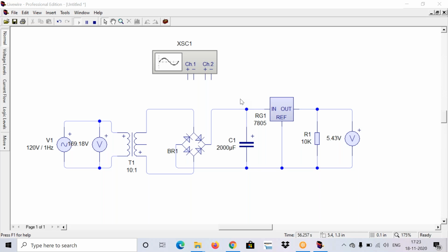Okay, I did not get you. Come again. No, sir. Our output is, we are preparing the 5-volt charger, then only you can go with the bridge rectifier. Whatever the circuit may be, whether it is a 5-volt charger or 12-volt charger, they use only the bridge rectifiers. Half wave and full wave rectifiers are not used in your circuits for better performance, because they cannot afford the 5 volts output, and your output may not be perfect if you use a full wave or half wave rectifier.